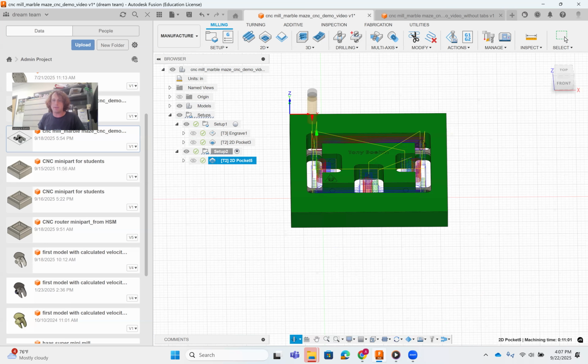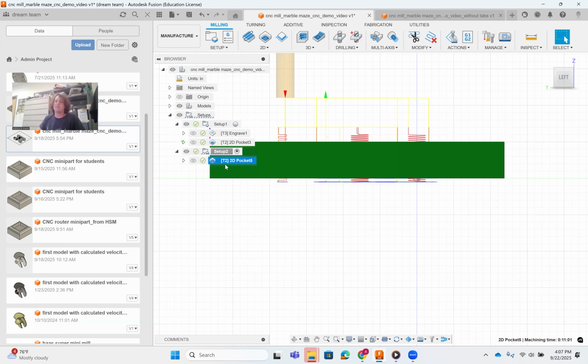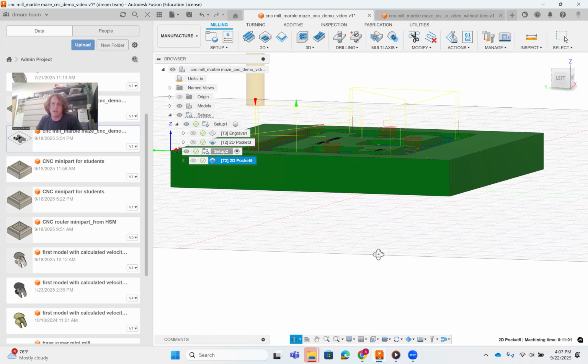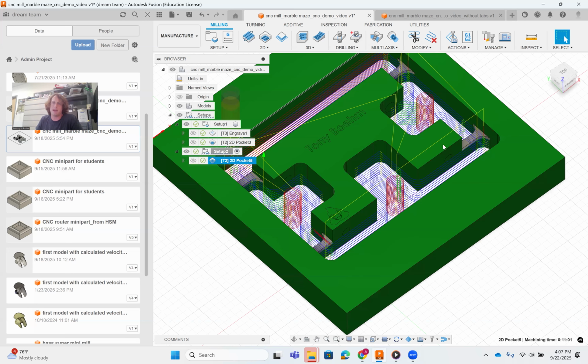And we will look at the side view here. And that should also be fine as well. I probably don't need to go 50 thou. I probably can do 25 thou. But we should have a 0.75 inch depth of cut with our 1/4 inch end mill. So that all should be just fine. Okay, cool. So we've made that path that both roughs and finishes all the geometry.